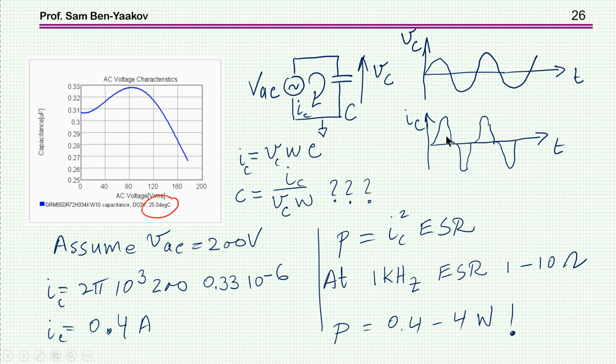So what does it mean that you take two values and you divide? It's not the first harmonic, it's just the RMS probably, or maybe the rectified and averaged. So the whole question of capacitance is really questionable from the theoretical point of view. However, it gives you a measure of what really happens as you change the excitation of this capacitor.